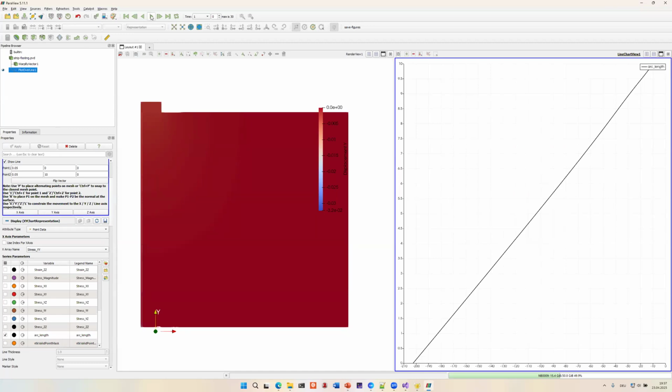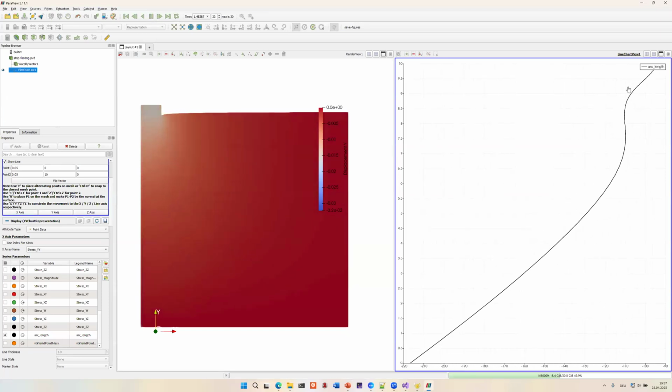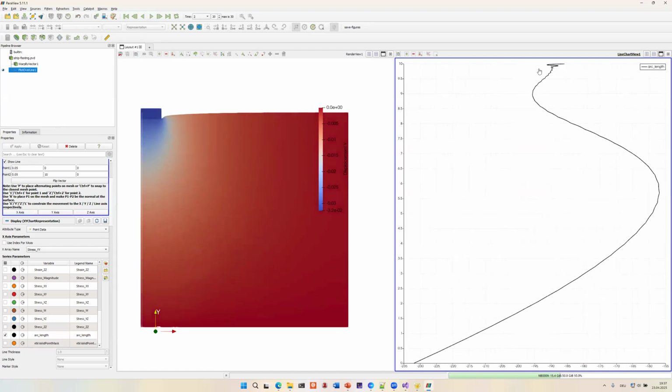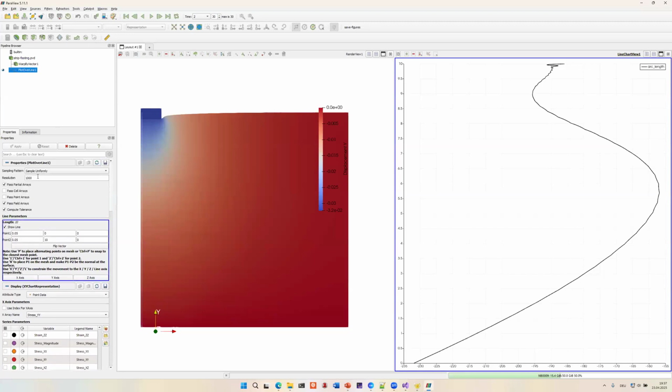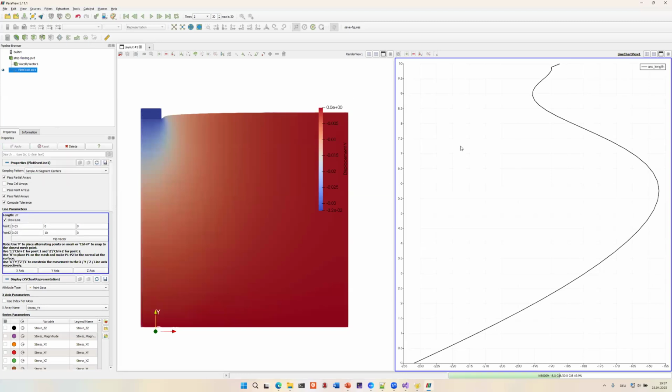And now if we're interested in how with ongoing loading this stress changes, you can look at a small animation, for example, where you see how the stress increases also at the top. You see that these smaller oscillations there, which is because ParaView samples along this line, and it's rather an extrapolation feature, let's say, of NUMGEO. It's not really the stresses that are fluctuating.